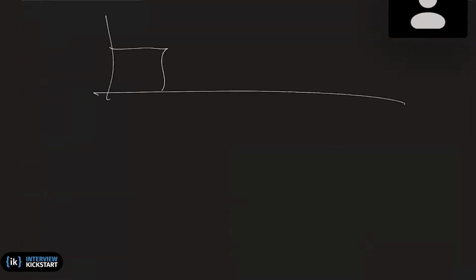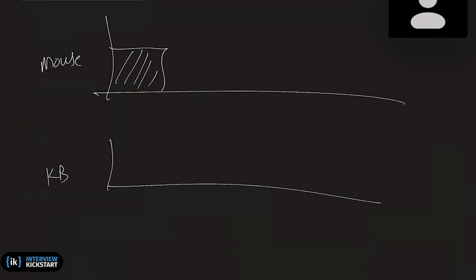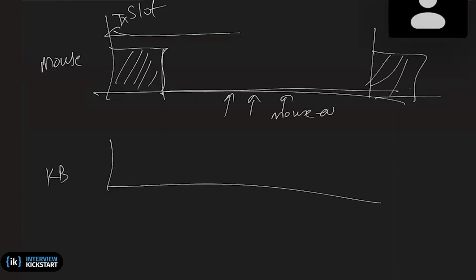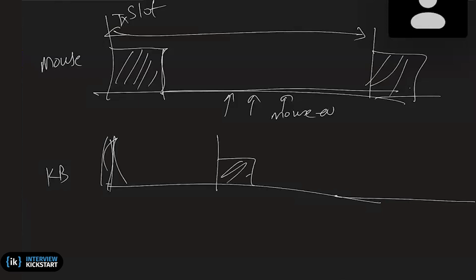So they periodically transmit. So this is, let us say, the mouse connection, and this is the keyboard connection. When there is an event, basically you may move the mouse, you may press the mouse. It doesn't mean that event is immediately transmitted to the master. So this is a slot at which they will wait for that slot to happen, transmit, this is the transmit slot, and then after getting the acknowledgement, it will go to sleep. And then any number of presses and movements that you do, mouse events, it will go in the next packet after this interval. Of course, this interval determines your response time for the mouse click and things like that, but they are reasonably small from a user perspective, and reasonably large from the power perspective. Similarly, the keyboard events. So this keyboard event may happen at this slot. And so they are basically interleaved slots.